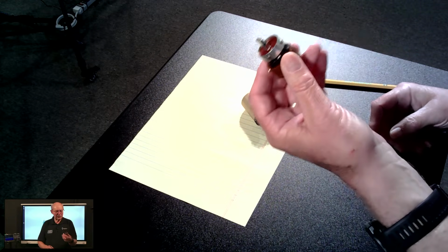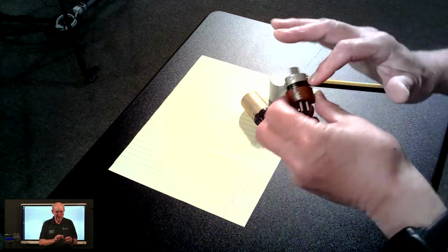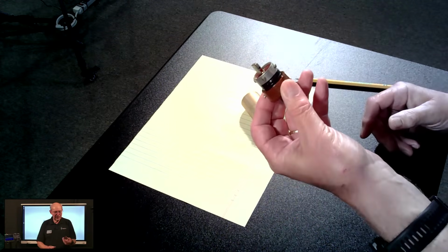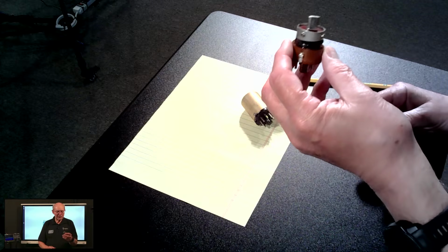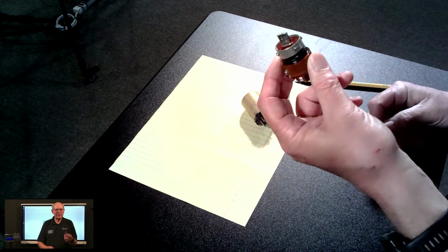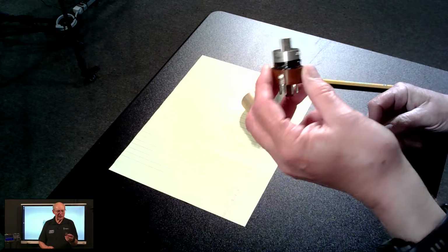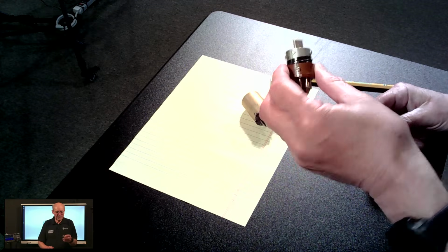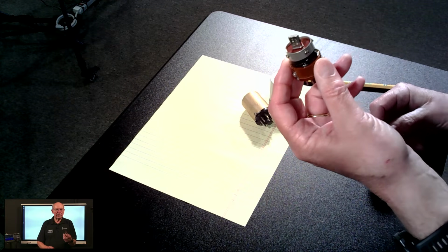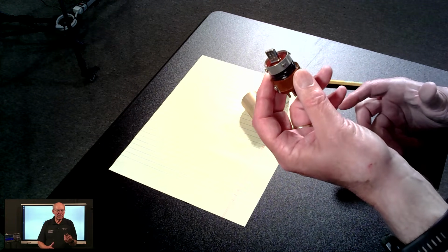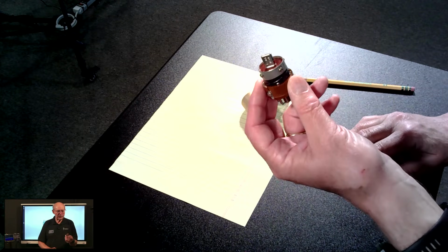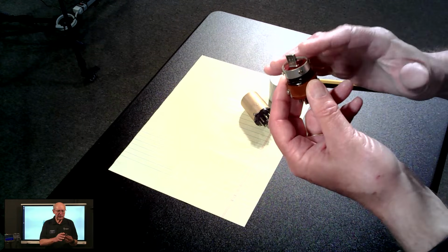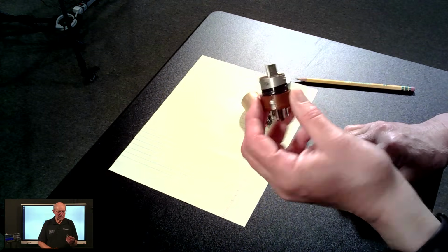You might be wondering. Well, there's a heating element here. And when you turn on the radio, this will increase in temperature to something that's well above ambient, might be 150 degrees Fahrenheit or maybe more. And then when it gets to that set point, it'll regulate the temperature within a fairly narrow range, isolating the crystal from the ambient temperature around it.